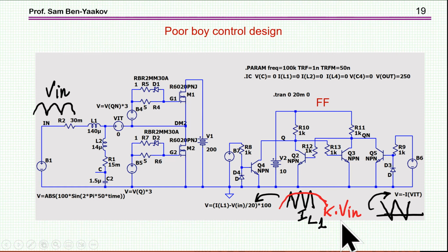So we have here two thresholds. One will keep the input current with this shape, because it's always clamped to the profile of the input current. And on the other side, it'll clamp to 0 with a little bit negative value to get the soft switching. So this is this flip-flop, and these are the conditions here. This is one condition, this is the other condition. This is just drivers to set and reset this flip-flop. Again, this is just for a demo.